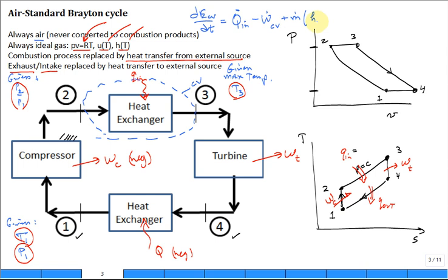Here it's coming in enthalpy 2, going out enthalpy 3, and then it brings in its kinetic energy 2, going out kinetic energy 3, bringing in potential energy 2, taking out potential energy 3, close parenthesis, and you say negligible changes of kinetic and potential, steady state, no shaft work going across the boundary of a heat exchanger, and we're left with lowercase q in, that's Q dot divided by m dot, is equal to, look at that, h3 minus h2. True? So this is H3 minus H2.